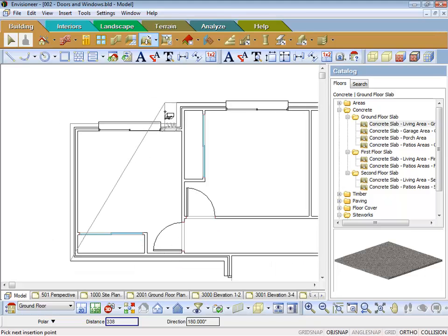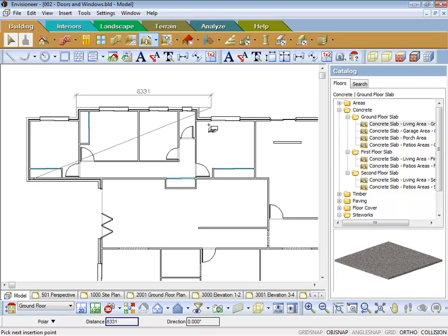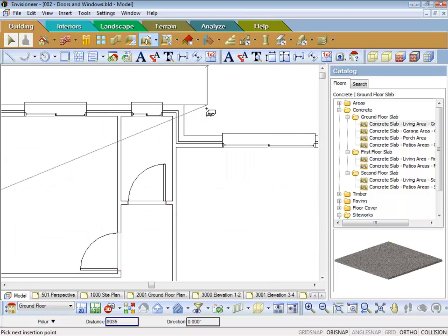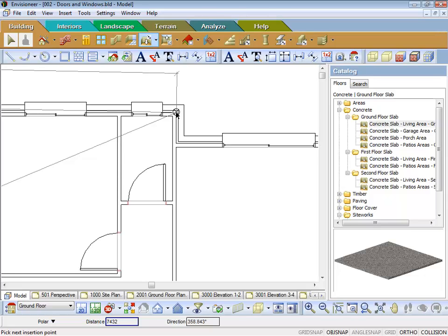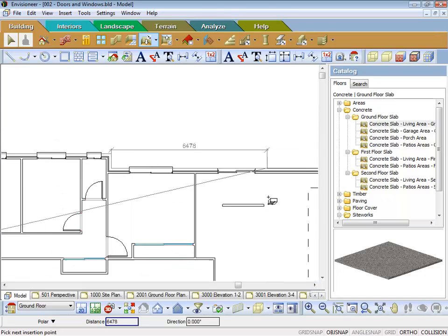I couldn't do that previously with my floor by perimeter because the perimeter selects the core of the wall, so therefore puts it at this point here, which is the outside corner of the stud or the plates, and I want to take it over all brickwork, so I'm basically having to use the perimeter option or picking point options.